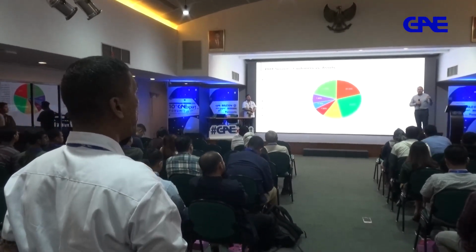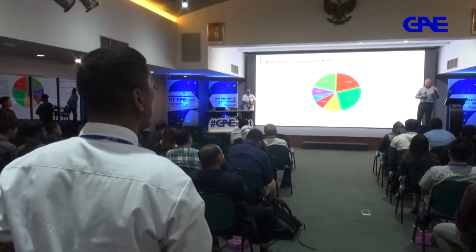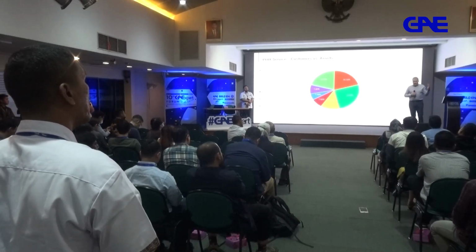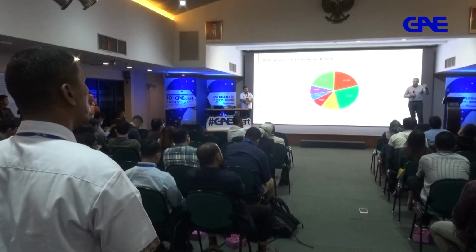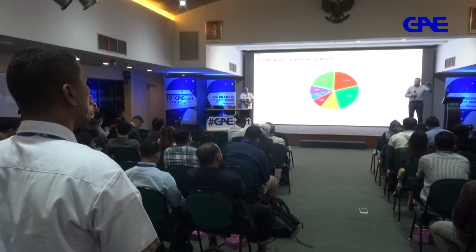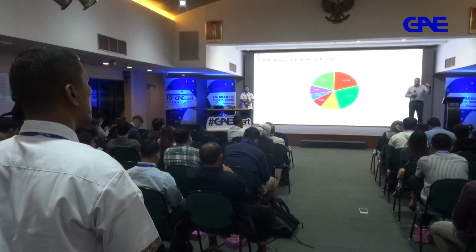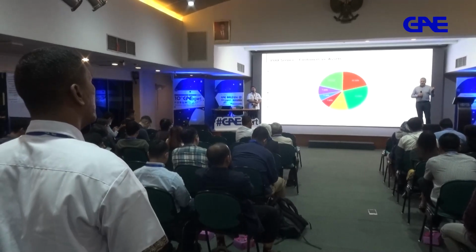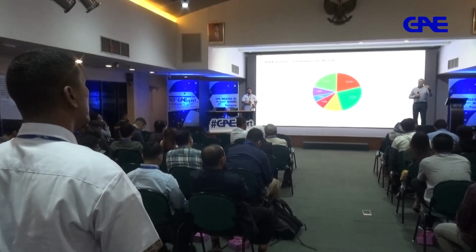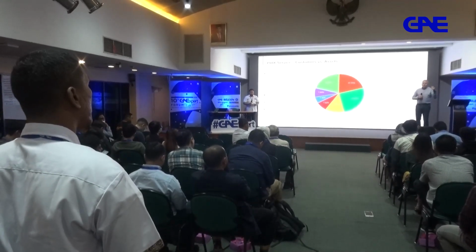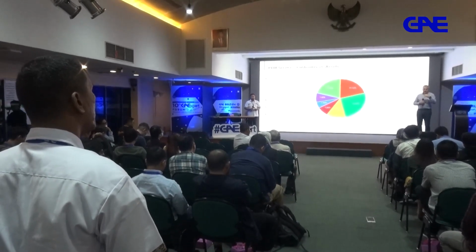So our equipment, of course, will acquire noise, right? And there are many ways to deal with noise. One has been recently mentioned in the context of gating. Another one is to raise the noise floor on our devices, and therefore that noise will not be considered when you look at a diagram. Now, you also have to characterize that noise. If that noise, for instance, has a corona kind of source, you will see it in the partial discharge diagrams.